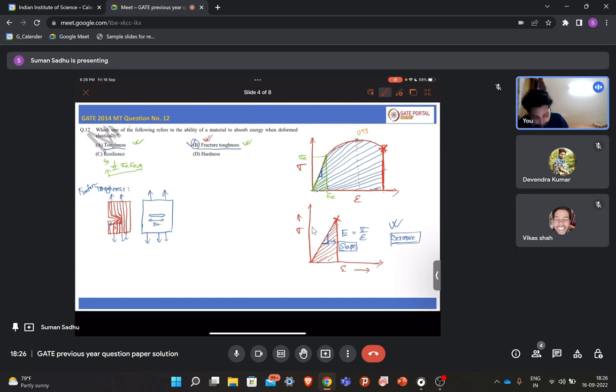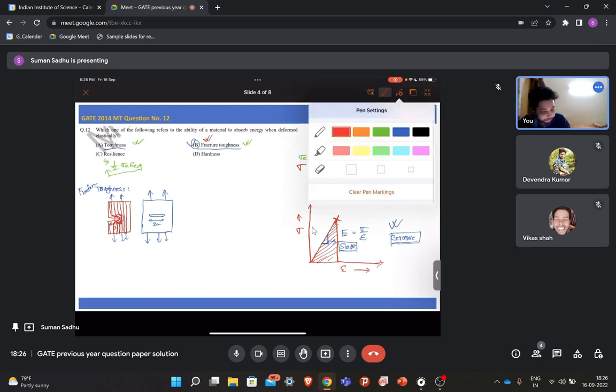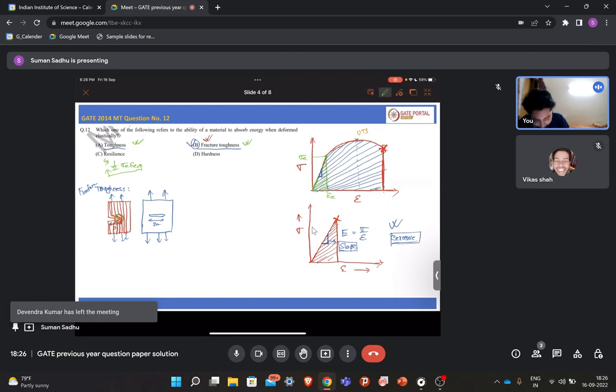So what will be the situation here then? The stress concentration will be very high near the crack tip, right? It is similar to if you have water flowing in a pipe, and then you bend this pipe, what will happen? Near the bend region, more water will go and bend. Similarly, the iso stress line will be like this only. So here stress concentration will build up. When stress concentration builds up, what will happen? Then this crack will start to propagate, right?